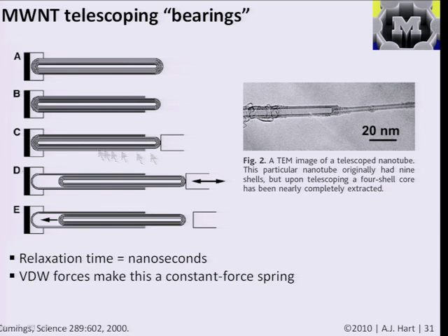And if you look at the paper, you would see that they measured the force necessary to pull the tube out. And effectively, because of the radial balance of the interaction forces, if you looked at this end on, the force necessary to pull this out is very little and is just related to the effective sliding resistance of the inside of the tube against the outside of the tube.